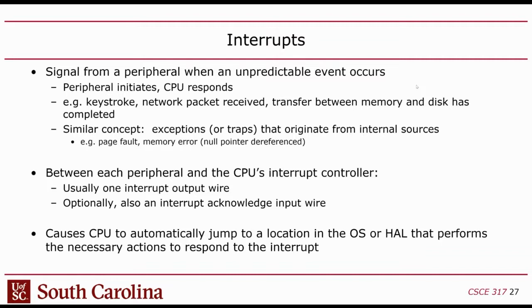interrupt service routine. Typically, depending on the interrupt controller, the CPU will know which interrupt tripped. Sometimes it needs to check a register to figure that out. But usually there's an interrupt controller that goes between these wires and the CPU, and is sophisticated enough to have separate addresses to send the CPU for each interrupt.